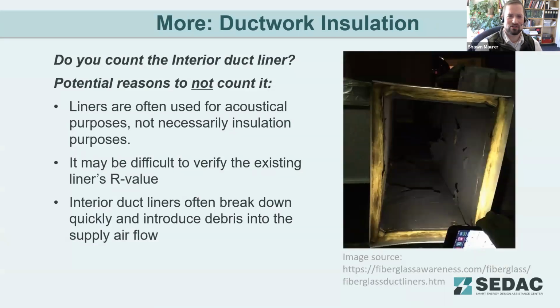But what about that interior liner again? So again, you can count it. There are some reasons you might not want to. Again, those liners are usually for acoustical purposes and not insulation purposes. So while they have some R value, it's usually not a significant amount. You're looking at maybe an R2 to R3.